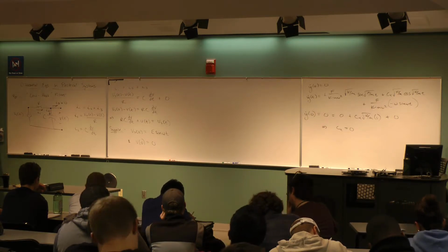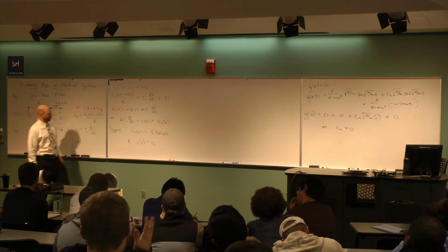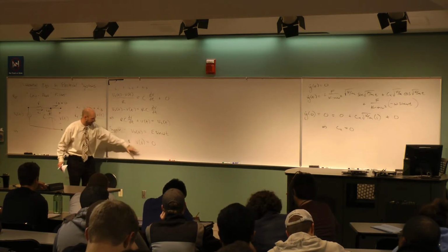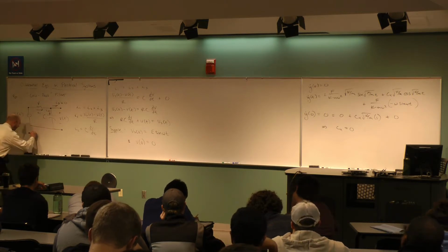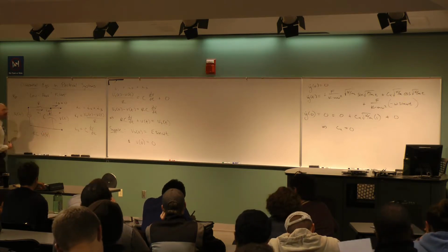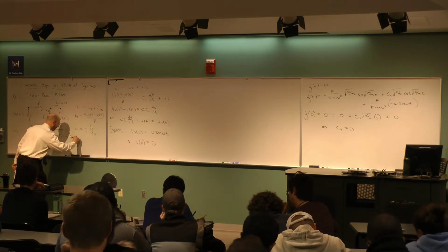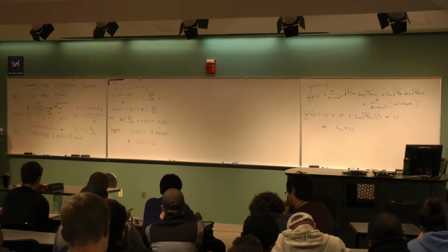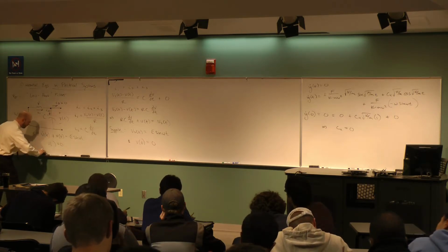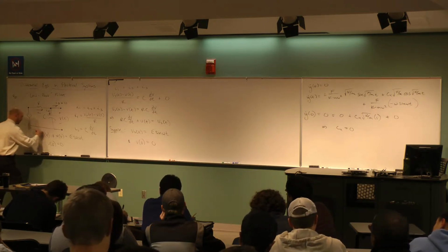If all of that is true, then let me go ahead and write as the problem statement here the resulting differential equation. It'll be this, with Vs being that and the initial condition there. So what we'll have is RC times dV dt, I'm going to write that as V dot of t, plus the voltage V of t is equal to the source, which is E times the sine omega t. Then I'll put my initial condition, which I need only one, V of 0 equals 0. This is the problem that I would like to solve right here. I'll put a box around it so we're clear.